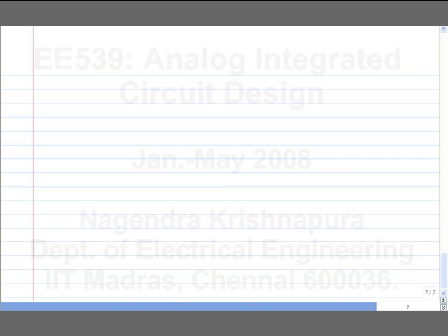One of the things I mentioned was that you have a right half plane 0 here, and that can be problematic, assuming that you use it in a feedback loop. Otherwise maybe not, but if you do use it in a feedback loop, you will have a problem. So any thoughts on how you will get rid of the 0 or change the value of the 0, move it into the left half plane? How might you do that? So here,